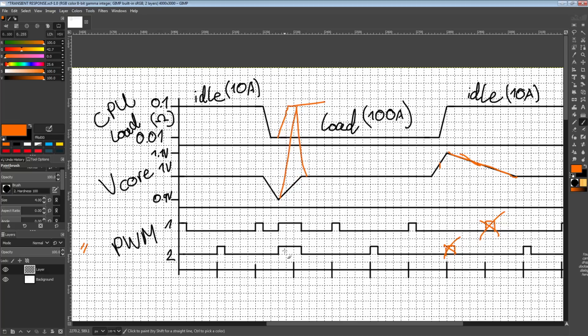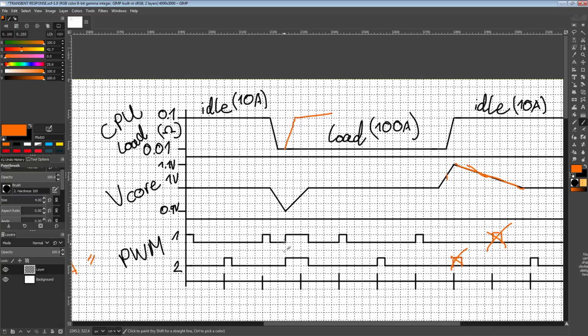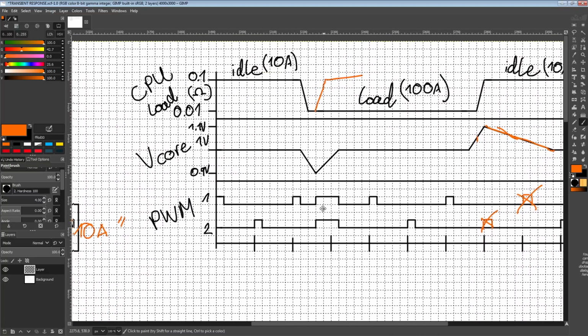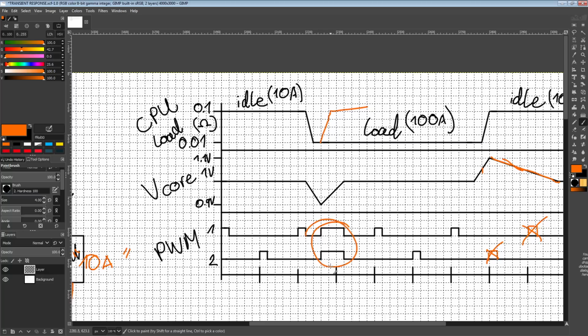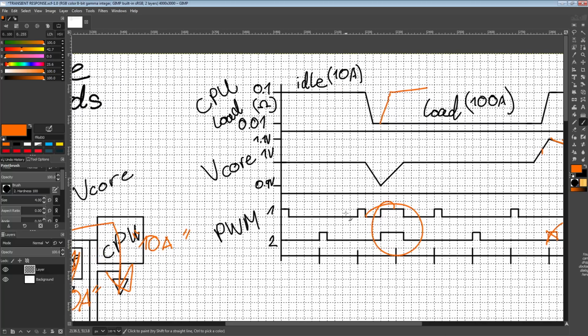The response came, but the voltage regulator totally missed the window. It just made a massive mistake. And that's also part of the reason why you don't actually see something like that on real voltage regulators, and why I said this is for convenience. There are other things that they'll do to improve transient response. They won't try to make one-pulse adjustments like this, but this is just the convenient way for me to draw this out.